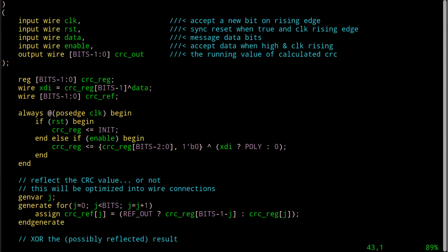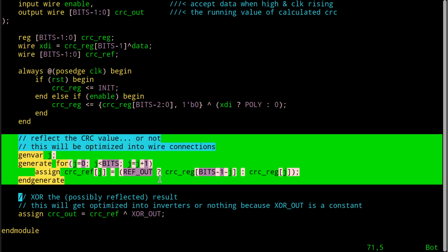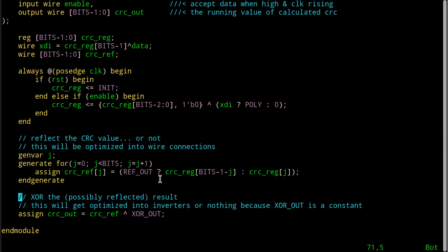So yes, now you know how to do it, and I've reminded myself again, oh yeah, I picked the wrong one. You need to do it right, okay? If you want to be efficient. Otherwise, you have to buffer up everything and then reverse it and build more circuitry and write more Verilog and all that other fun stuff. So let's look at this generate. We've talked about the whole thing. We gave you the context and show you where you can get the background. Let's look at this generate statement.